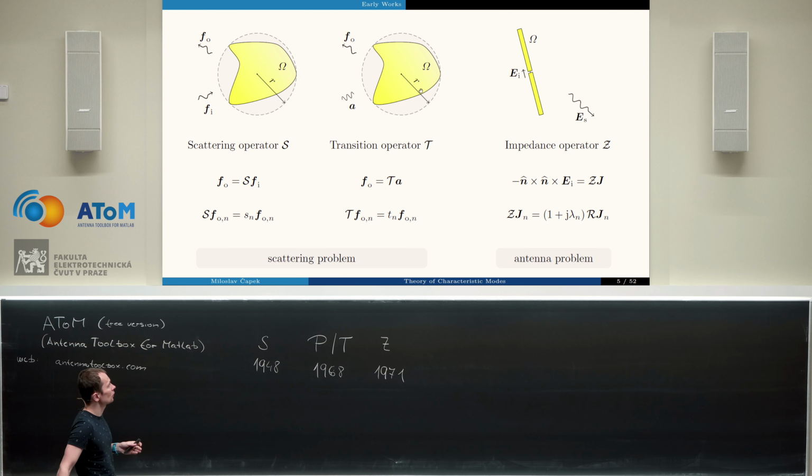And therefore, we may think that this antenna problem, in fact, has no assumption like this, that the quantities being inside the circumscribing sphere are maybe ill-converging. But during this talk, you will see that this is the case as well. And we have to be very careful with investigating quantities which are tightly related to a near field with characteristic modes, such as the Q factor of your antenna or input impedance and so on.